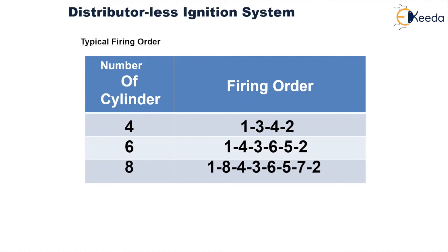In case of a multi-cylinder engine, the ignition system needs to consider one more problem, and that is of the firing order. If we consider a four-cylinder engine, here we are seeing that the firing order is 1 3 4 2, that is the consecutive cylinders are not going to fire simultaneously or consecutively. By firing, we mean the development of expansion stroke. If we consider that one after the other, the cylinders fire sequentially, that is, expansion stroke is produced in the cylinder sequentially in the order 1, 2, 3, 4.